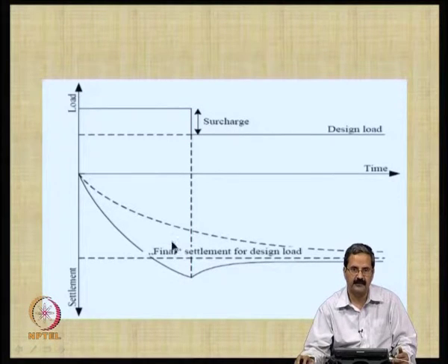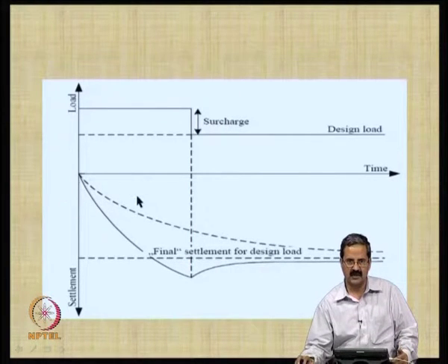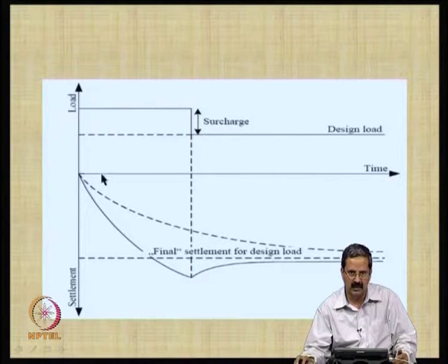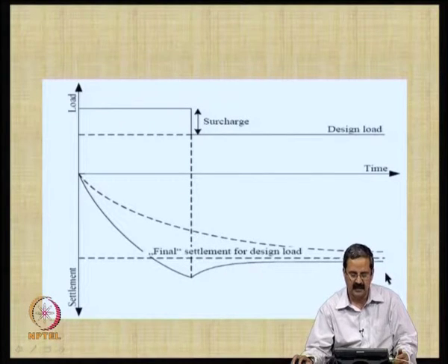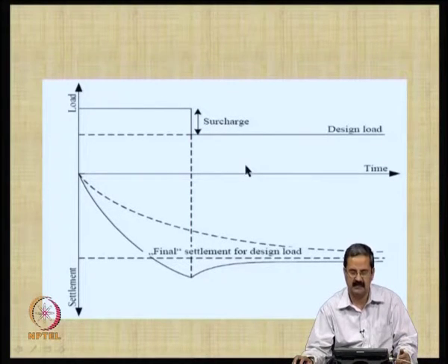To reach that settlement level, consolidation in a regular manner takes a very long time, maybe about 4 or 5 years, but with this you are able to preempt the whole consolidation, and even if there is a release, it is alright. You are able to achieve that settlement in a shorter time. That is an example of what we want.